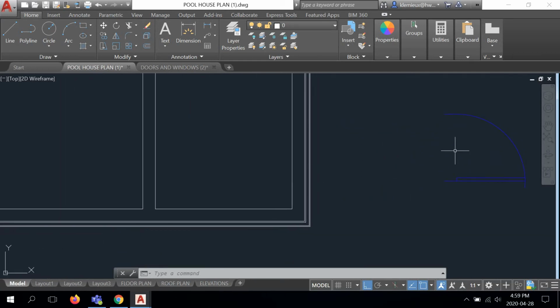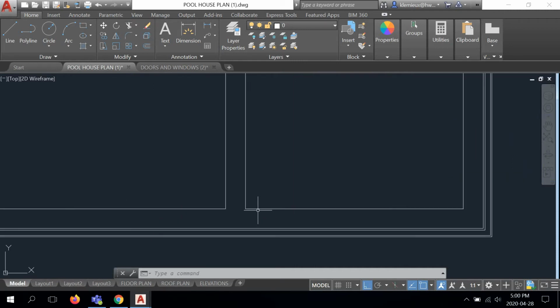Now, this door is going to snap into this interior wall. But how far should it be from the wall, the adjacent wall, the exterior? Well, the best case scenario would be to keep it right against this wall here, but you don't have to. I mean, typically builders would leave it a couple of inches or so away from the wall.